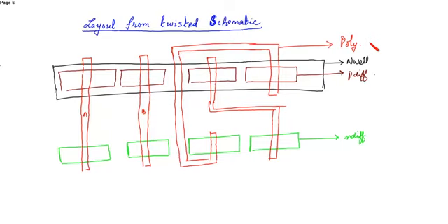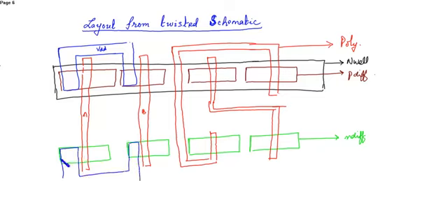Okay, now complete this inverter. The source is connected to VDD, source connected to VDD, then the source of the NMOS is connected to ground, then in the transmission gate the two sources are connected and the two drains are connected.